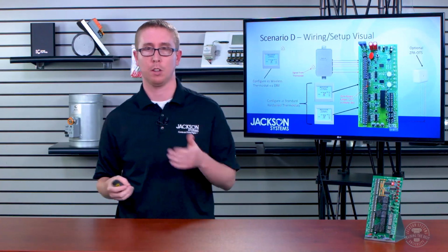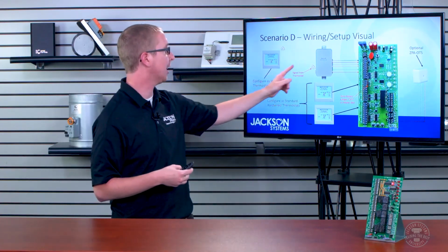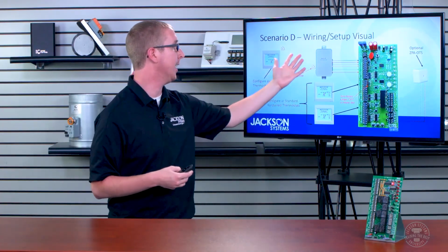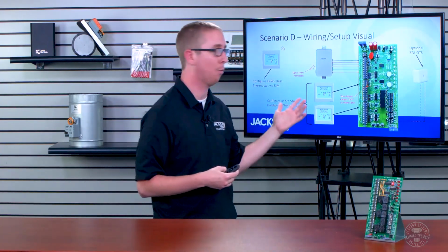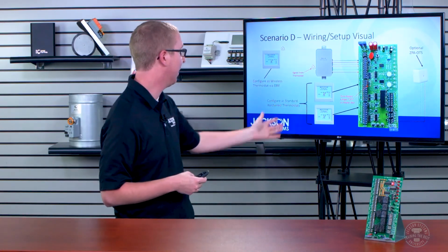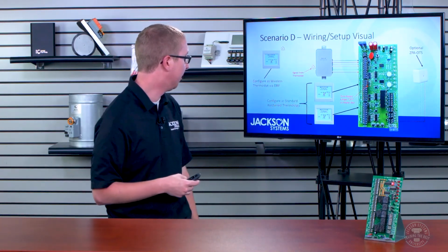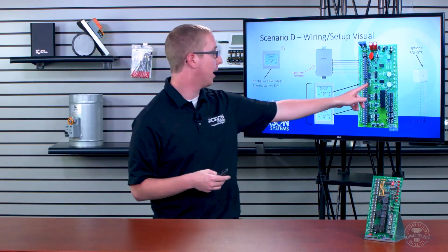And here's what it looks like. So this is your one wireless thermostat communicating to this EIM. The EIM you would just wire into the zoning panel thermostat terminal as if it were the equipment. Nothing fancy there. And then you have 2 standard Vision Pro thermostats that you would just wire directly into those terminals.